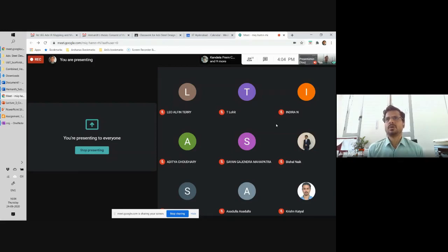If you have an I section with very thin plates, you are not likely to have very high levels of residual stresses. But an I section with very thick flanges, of the order of 2 inches thickness, for example, 2 inches is 50 mm thick, or above 100 mm thickness, such flanges will definitely have a very large level of residual stresses.